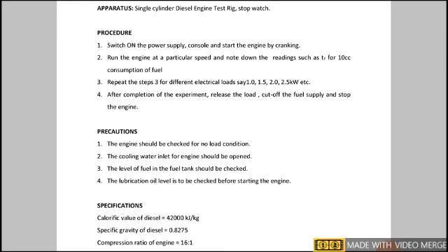So once we change the electrical loading, we need to note down the different readings such as the manometer reading and the fuel consumption reading along with the engine speed.